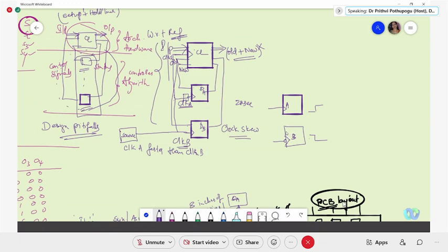Like the lapse that you get, if you need to synchronize, a natural thing we think of is using a D flip-flop, but that introduces skew, we are saying. So never use two different edge triggered things. Use either both positive or both negative.